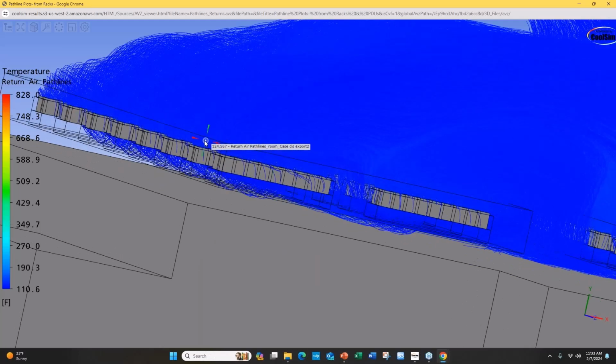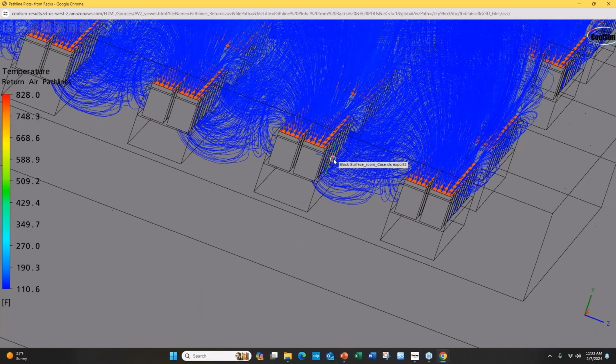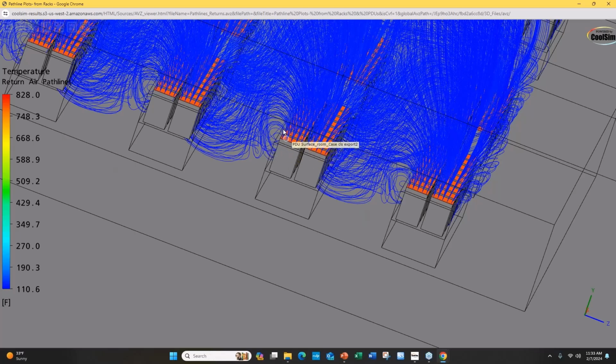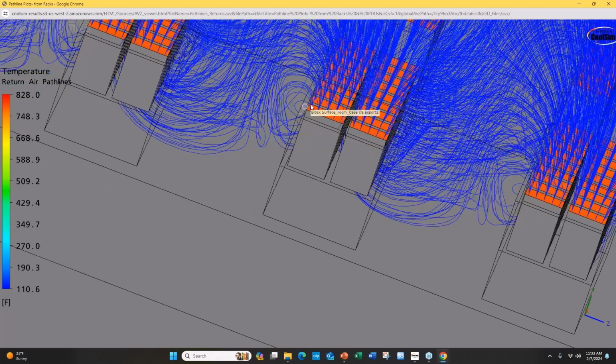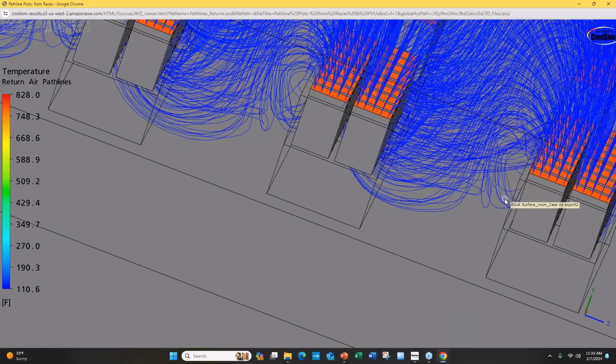And then what you say is, okay, what do I do to solve it? Well, just like in hot aisle, cold aisle containment, yeah, you can see them going down right there. You see how that one goes right down underneath? This is a very common thing that I see, is the exhaust gets sucked into the intake. The reason for that is the intake, of course, is running at a lower pressure. And the other reason for that is usually a screen right here, which there is in this case, and that screen is causing a low pressure on the back side of it. So down low near the surface of the roof, you've got a lower pressure than you do up on top. And what that does is tends to pull the air from the exhaust down into the bottom. So they just recirculate on themselves, causing efficiency to drop off quickly.